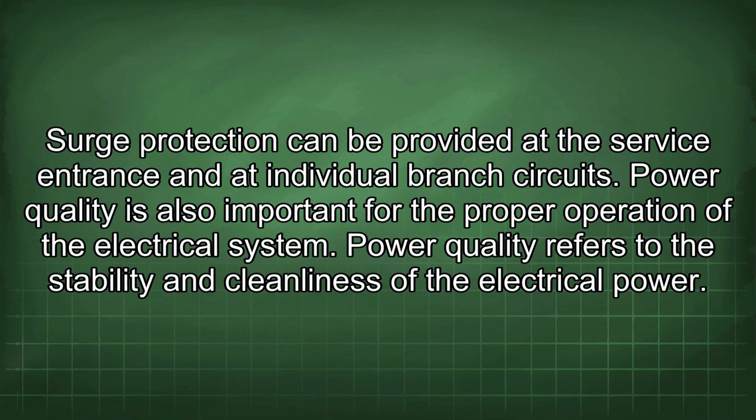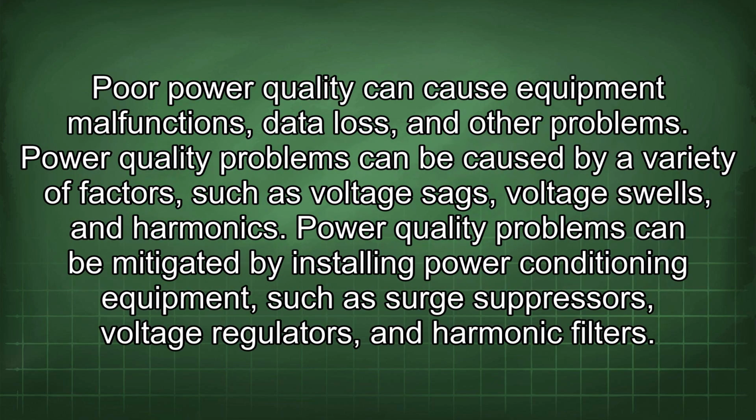Power quality is also important for the proper operation of the electrical system. Power quality refers to the stability and cleanliness of the electrical power. Poor power quality can cause equipment malfunctions, data loss, and other problems. Power quality problems can be caused by a variety of factors such as voltage sags, voltage swells, and harmonics. Power quality problems can be mitigated by installing power conditioning equipment such as surge suppressors, voltage regulators, and harmonic filters.